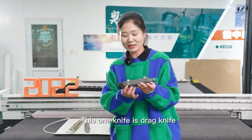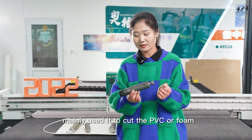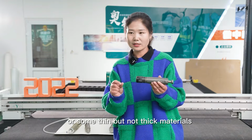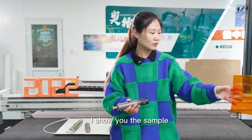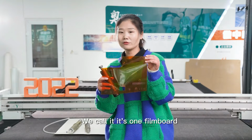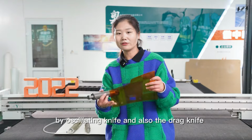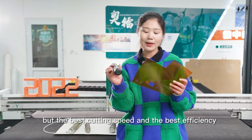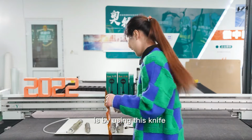Okay, this one knife is the drag knife. Mainly use it to cut the PVC or foam or some thin but not thick materials. I show you the sample. You can see this one. We call it foam board. This material can be cut by the oscillating knife and also the drag knife, but the best cutting speed and the best efficiency is by using this knife.